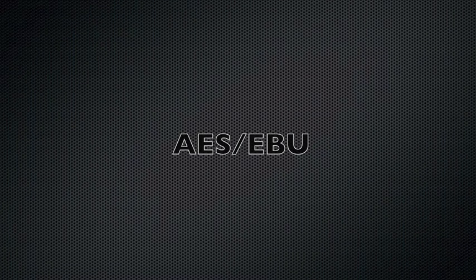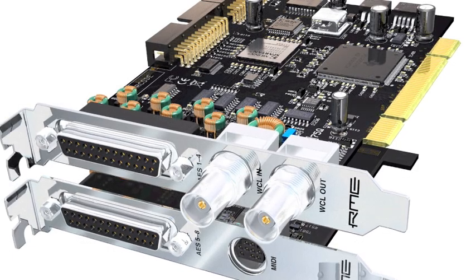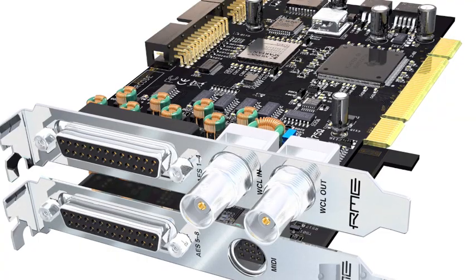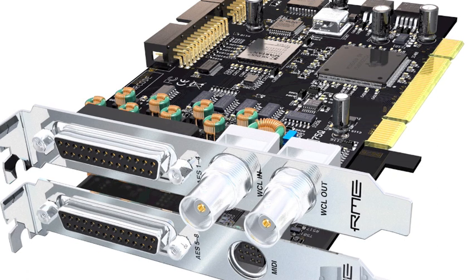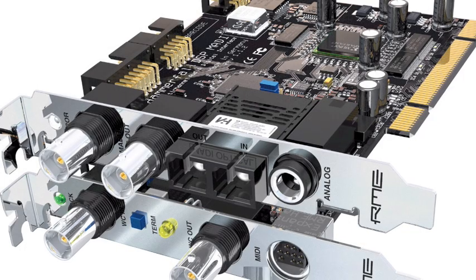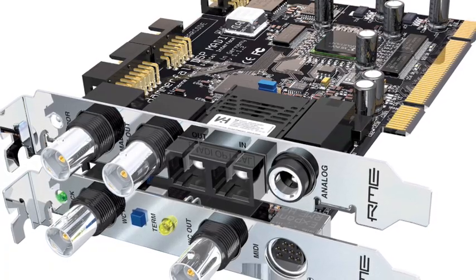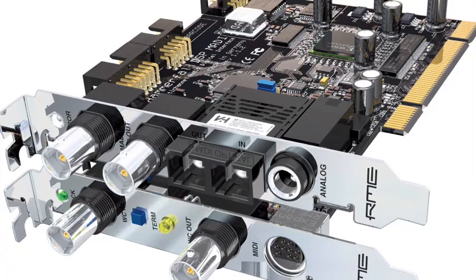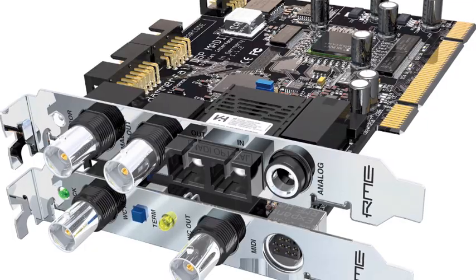AES/EBU or AES3 is another protocol for carrying digital audio signals. In professional audio interconnections, it uses either XLR cables or D-sub connections for carrying 16 channels of digital audio. MADI stands for Multi-channel Audio Digital Interface and is a more advanced transfer protocol that can carry up to 64 channels of digital audio in high sample rates.